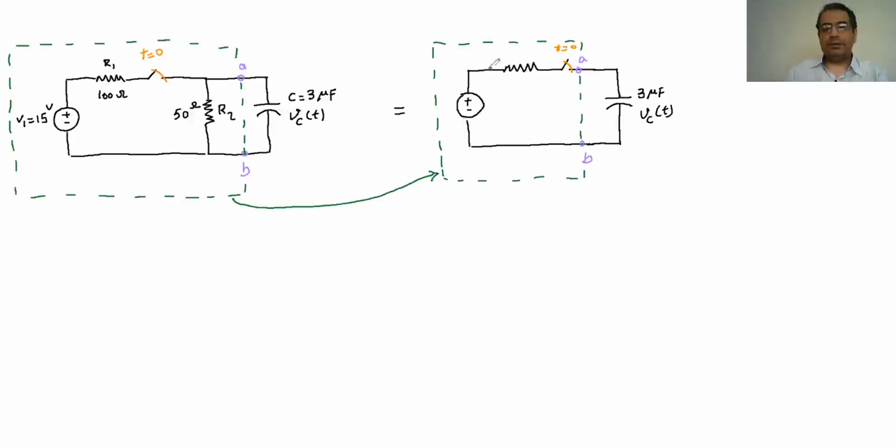So remember when we had the Thevenin, to find the Thevenin resistance, the easiest method, if we didn't have any dependent sources, which we don't, was to zero the sources, and then the equivalent resistance would be the same as the Thevenin resistance. So if I zero the sources, when we have a voltage source, you just replace it with a single wire.